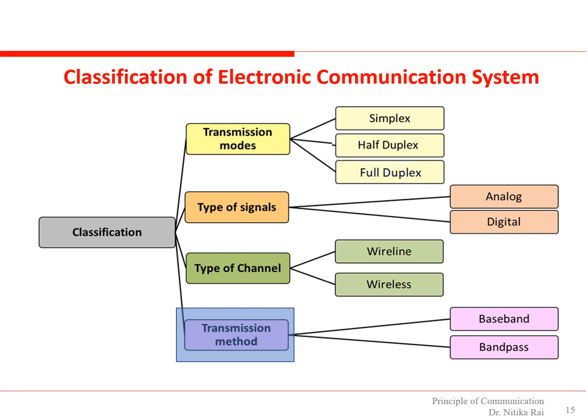We will need a carrier. We will need to superimpose this low frequency baseband signal onto a carrier that can carry it over long distances. This carrier here is nothing but a high frequency, constant amplitude signal. This process of superimposing a low frequency baseband signal onto a high frequency carrier signal is called modulation.